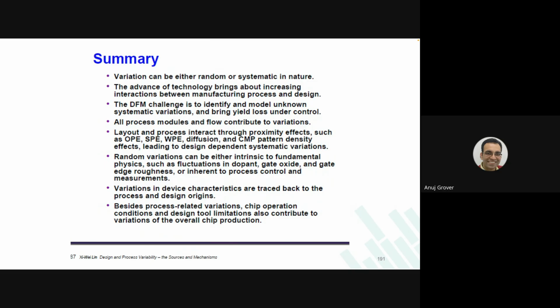So we actually designed a completely new verification methodology where we said, no, this current is no longer Gaussian. Since it is not Gaussian, we had to use different distributions. We use the Weibull distribution to model minimum current in any bit slice. We will talk about that in one of the next lectures. But when you enter the industry, you will realize there is a much stronger focus on accuracy today than it was even when these slides were made. Okay. So be prepared for that.